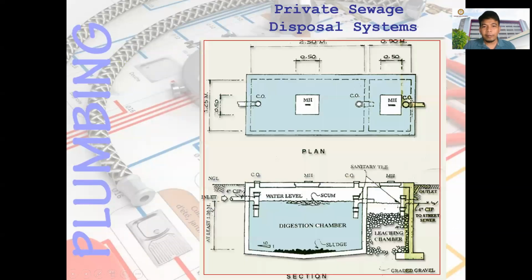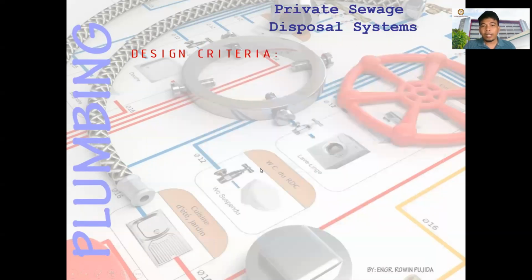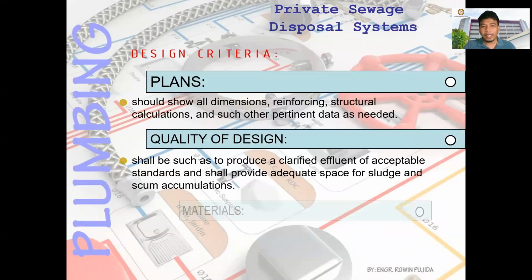So for this one, it should have a 1:10, but in our design now, we have 1:5 slope for the digestive chamber. Okay, so to collect the sludge and accessible by manhole. So this is 1:5. Okay, and then as of this discussion, this is 1:10. But you can use 1:10. Okay.